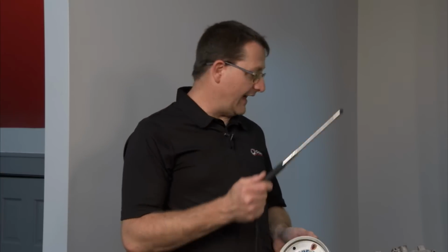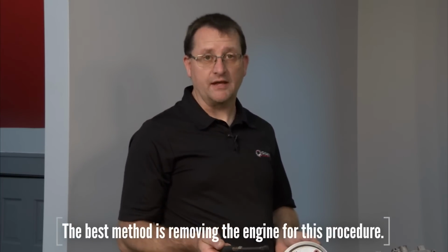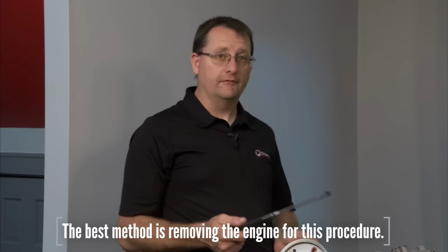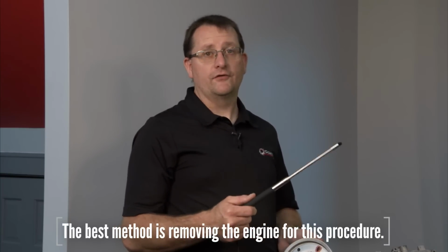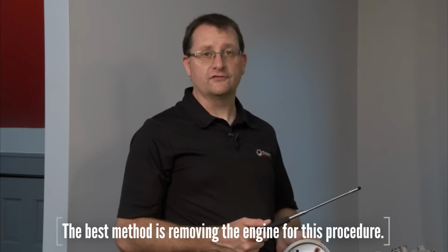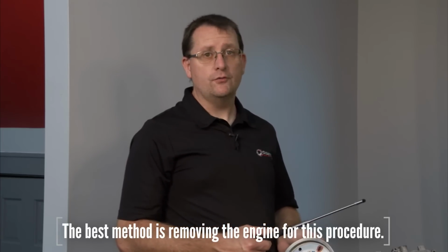Now, first off, I have the engine out of the car. I highly recommend that you do the same. If your car is a Boxster, either an S or a base, there is a good possibility you could do this in the car. It is going to fight you, you can't do as good of a job, and things are going to take longer than they will if you just bite the bullet and pull the engine out of the car. If you have a 911 variant, it is very difficult to do this in the car, and I certainly would suggest that you remove the engine.